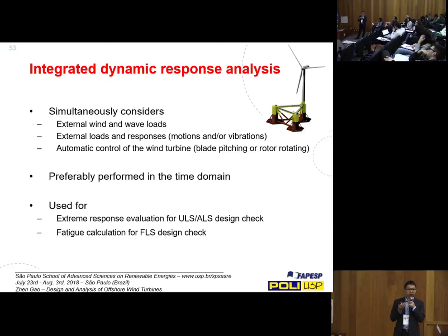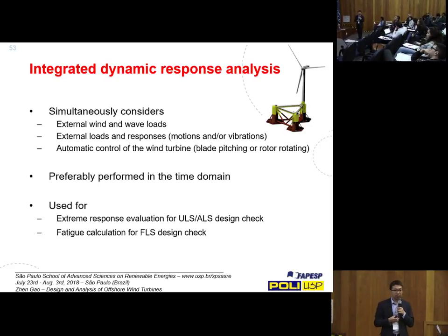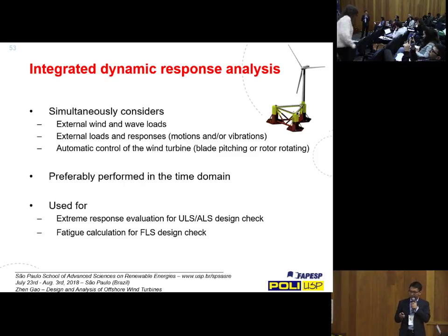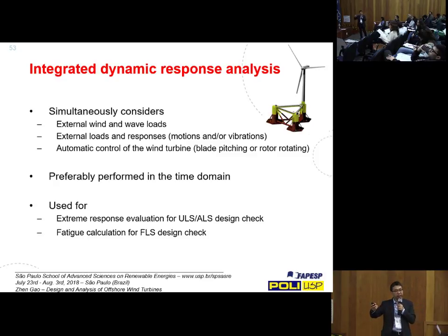And what is important to notice is that the wind turbine loads basically come from the lift and drag, which is a quadratic term with respect to the velocity. So basically, they are nonlinear forces with respect to velocity. So you have to do this in a coupled sense, so that you solve the motion, get the loads and then solve the motion, and then do iteration to predict the loads at a deformed position and so on. So these are important and are preferably performed in the time domain, and when you consider also automatic control of the wind turbine.